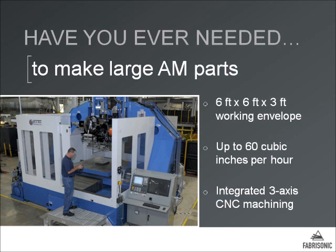For many of our armor applications and structural custom materials, we do this where we lay large sheets of material and weld continuously. This affords us the ability to make parts at about 60 cubic inches per hour. When we start doing shapes and parts that have complicated geometry, this quickly falls, but certainly we're typically in the range of 20 to 30 cubic inches an hour.